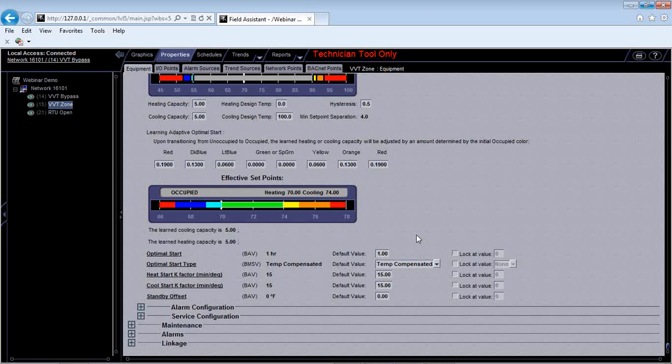So it's going to generally change those, and when you have a third-party BAS system reading one of these controllers, they get confused when they're trying to maintain 70 degrees on their side, but the controller is saying it's maintaining 70.5. It causes problems and confusion, and it's something that you don't want to have the headaches of dealing with, so you can just lock out your optimal start.